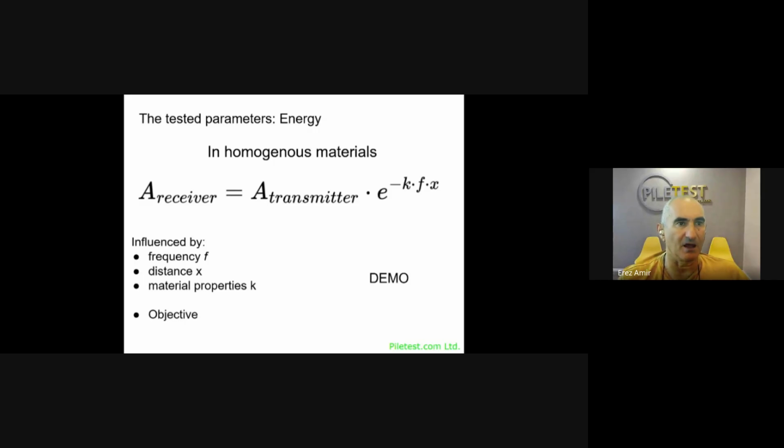So that's why the rule of thumb is usually one access tube for 1 foot of diameter. That means that you have about 80 to 90 centimeters between the tubes, which is a very good distance for testing. You can really see good size defects and not waste too much money on access tubes. Hope that answers the question.